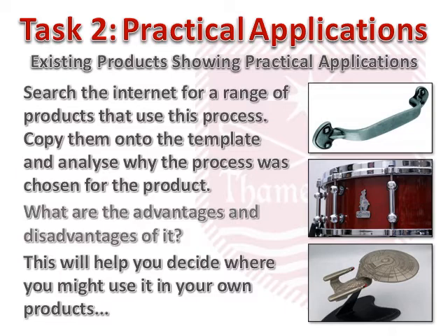The second one, the little badge or the drum, was made in that way because the detail you can get with casting allows you to make badges and little objects like that quite well. And the same thing with the little enterprise down the bottom. It can give you quite a nice finish. Quite a lot of detail can be put into the mold, and also with the drum badge, you can use the process again and again and again. You can use the same mold to produce the same badge multiple times. So when you come to badge up your different drums, you can use that to repeat and batch or mass produce that particular part.